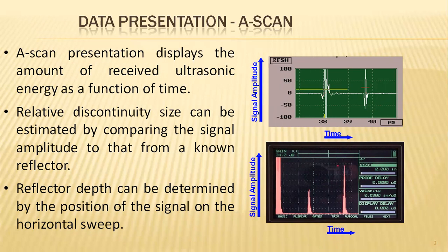The relative discontinuity size can be estimated from the damping or amplitude variations at different frequency levels, identified on the CRT screen. And the depth of the reflector is determined by its position on a single horizontal sweep.